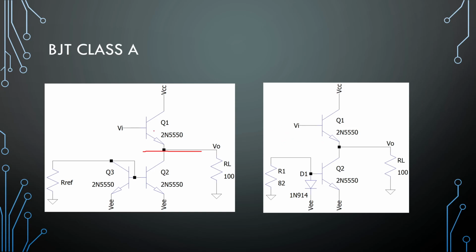Okay, so first thing that you always want with these circuits is you want your transistors to match, especially so that the saturation currents of both of these transistors are exactly the same. Then the VBEs down here can match perfectly when designing a current source.